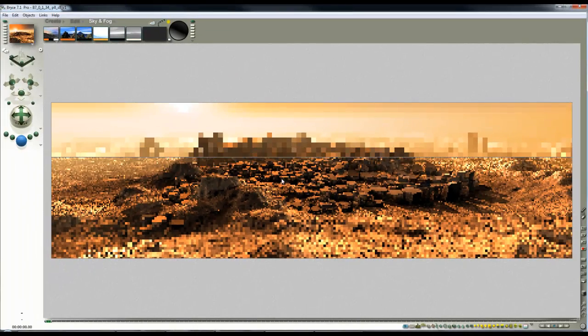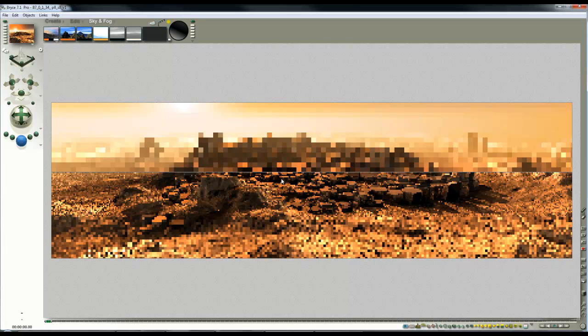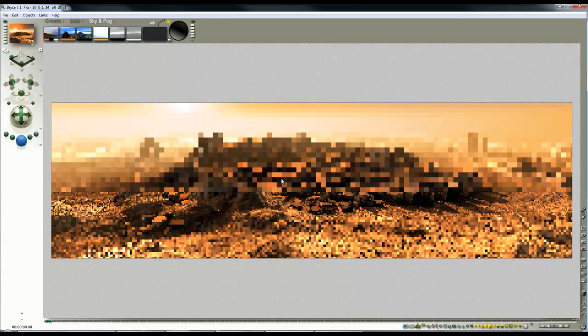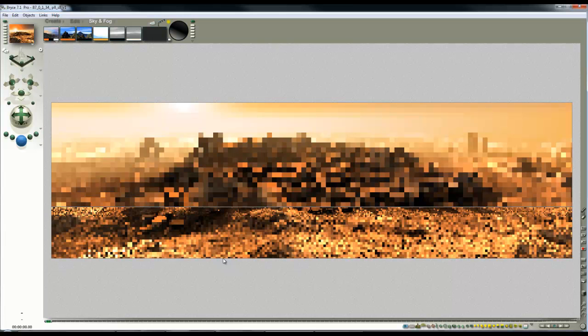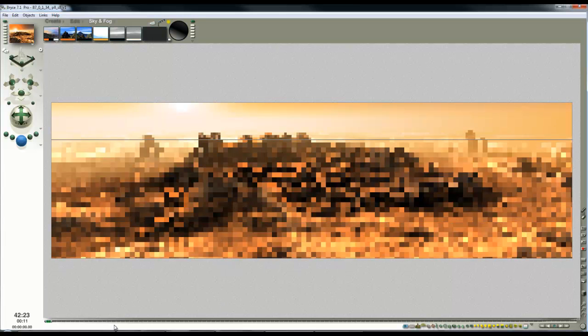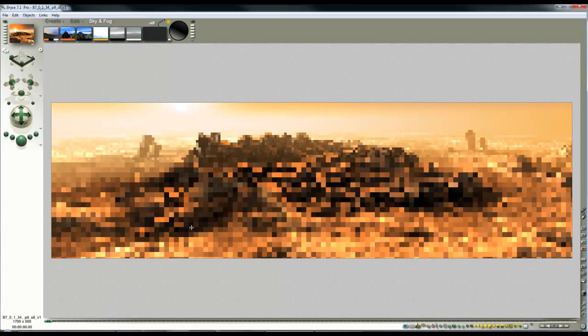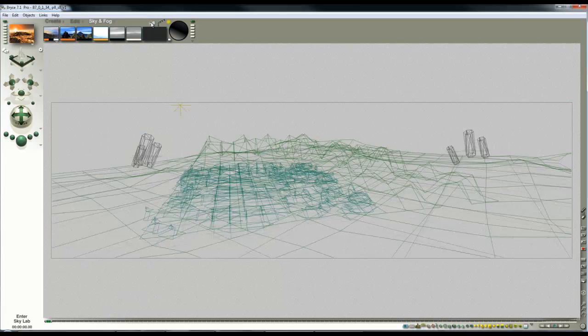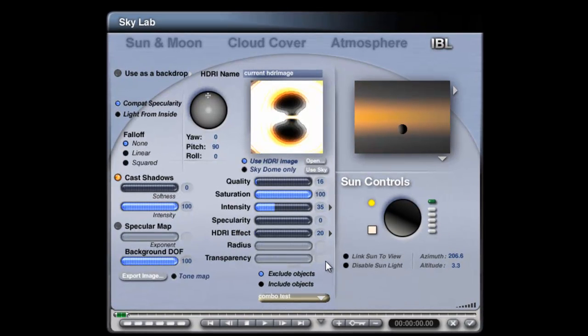So now what you immediately notice is this is a very slow render, and this is on a fairly fast machine as well. I mean, the quality of lighting might be very good, but even at 16 rays per pixel, it's taking three quarters of an hour. And the reason for this is, unlike with a Bryce 7.1 scene where it's been set up with image-based lighting, HDRI lighting, the true ambience optimization will not be checked by default. This is something that occurred in Bryce 7.1.